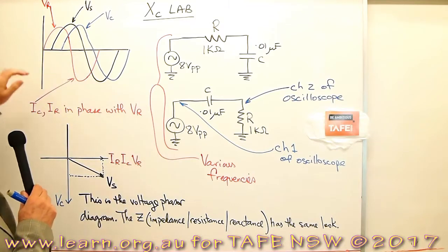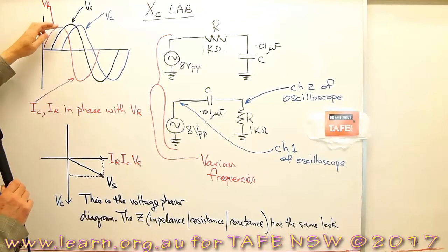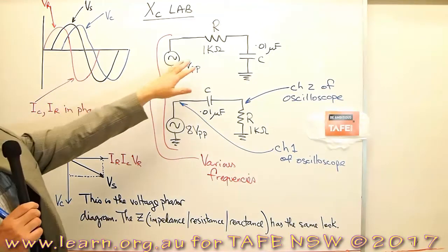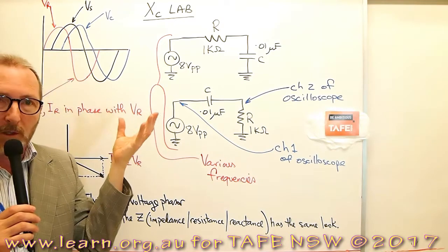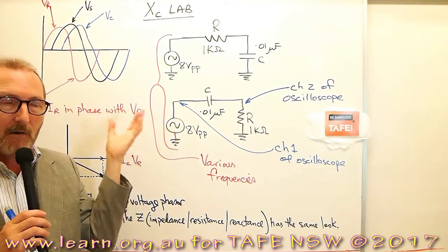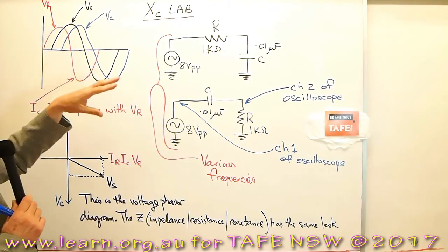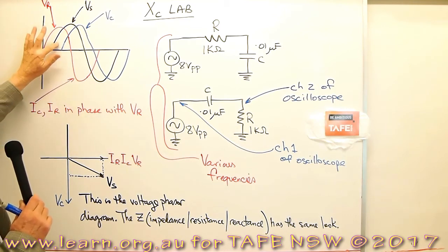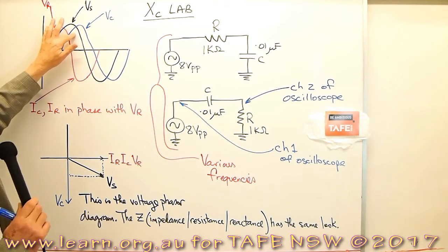And I've illustrated this on the board up here, showing the voltage across the resistor and also the current across the capacitor in this RC circuit, and the current in general, because it's a series circuit and the current is shared by all three components. So IC, IR, I circuit, VR are all leading the supply voltage, and the supply voltage is leading the voltage